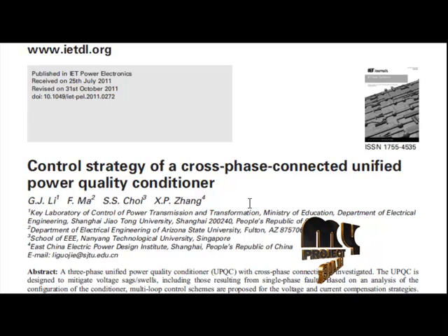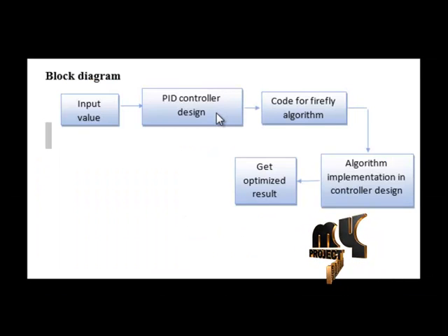Our main objective is to regulate the supply voltage to the load by the cross connection of phase control method. Here we use series and parallel voltage source converters for access to the input voltage, interconnected through a common DC link capacitor. The response of the UPQC is load balancing, power factor correction, voltage harmonic mitigation and current harmonic mitigation. Manipulated variable.